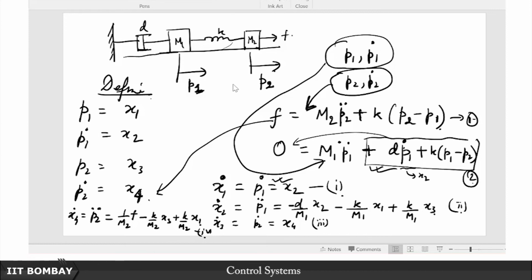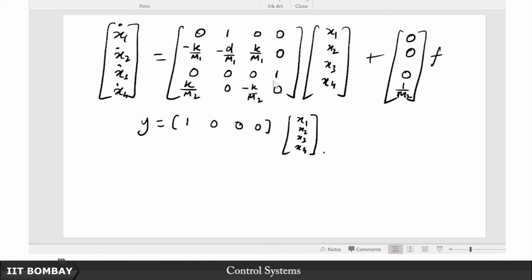So instead of taking the Laplace transform of these individual equations one at a time and then eliminating variables and obtaining the transfer function, why not just go into this model based approach, this state space representation, and take sI minus A inverse, pre-multiply it with C, post-multiply it with B, and you have the transfer function. So you verify by both methods that indeed it agrees.